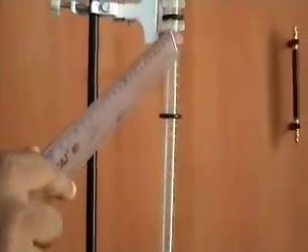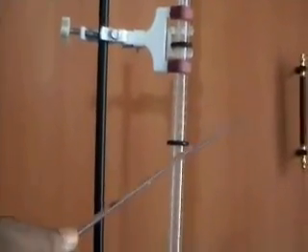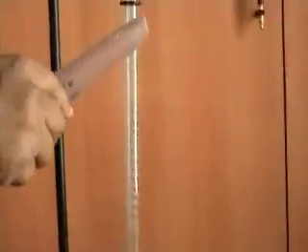Since we are taking the average height here, your values will always be more accurate when the distance between the 40 cc and 45 cc marks is as small as possible. For example, we are taking 5 cc here. Had you taken 2 cc, the marks would be closer together and your average height would be much better. But we also have to note the time conveniently. So an optimum value of 5 cc has been fixed for this experiment. I will show you later how to take the height of the respective graduations from the axis of the capillary tube.